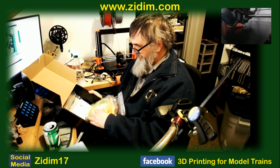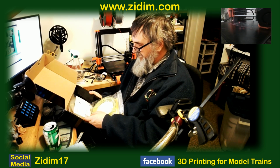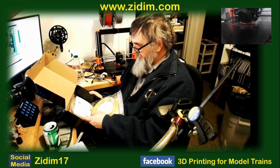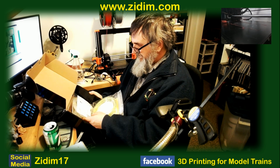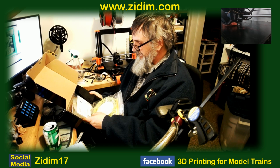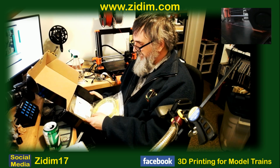So, another one, a high temp PLA, which is one I might be putting to work right away. No colorants in this one. More flexible and durable than standard PLA. Can be annealed at 80 to 130 degrees Celsius for improved temperature resistance. An annealing oven is something I have to add in. What I was thinking of doing is getting an old toaster oven and see if I can make that work.